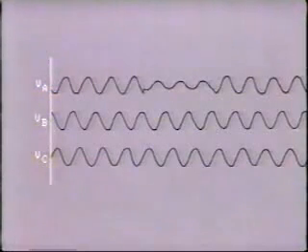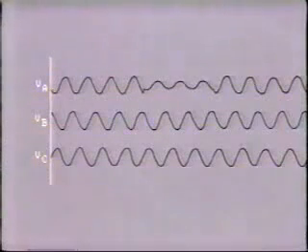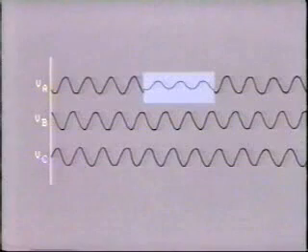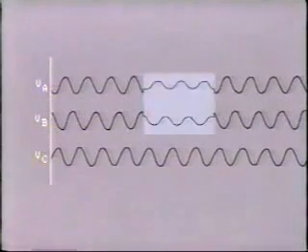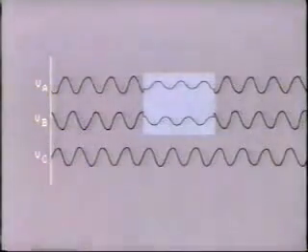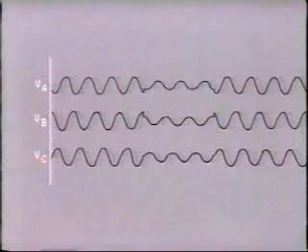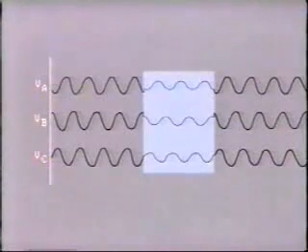Bus voltages are important because they can usually tell us what type of fault has occurred. Low voltage on one phase indicates a single line-to-ground fault somewhere on the system. Two low voltages can mean a line-to-line or double line-to-ground fault. Three low voltages indicate a three-phase fault.